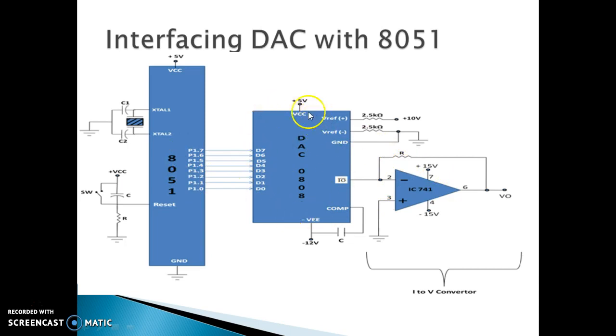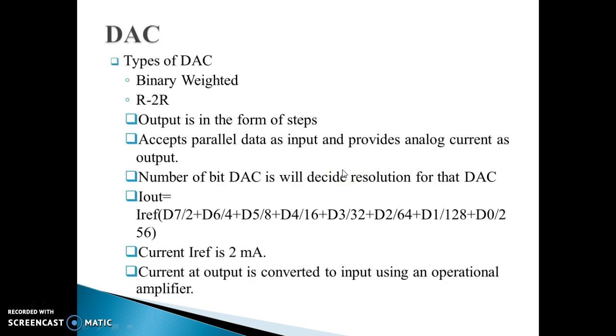Now this 0808 DAC cannot communicate with the microcontroller using I2C, as it is not I2C compatible; there are no SDA and SCL lines. A different DAC would be required, one which has SDA and SCL lines.